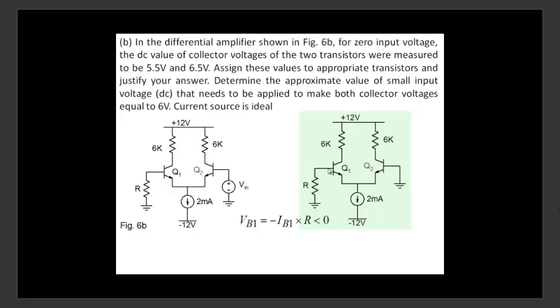So there is going to be a base current flowing here, and base current means that there's going to be a voltage at this particular node here, minus IB1 R at this point. Note how the base current starts from here and flows into it. So this node would be a little bit negative, minus IB1 R, as compared to this particular node. That's the implication of R when you put R here. This node is negative compared to this.